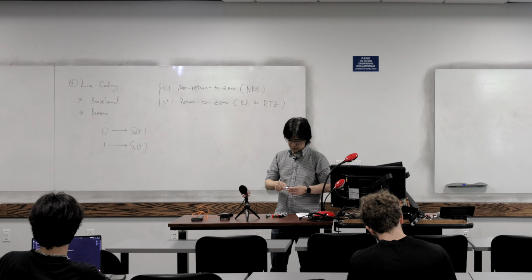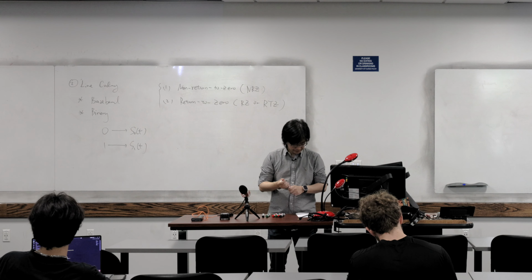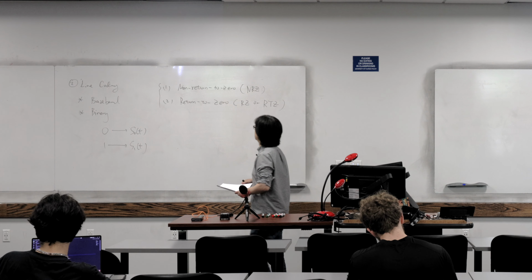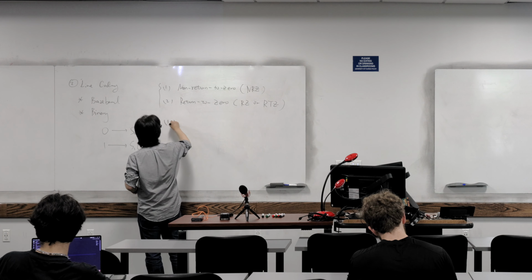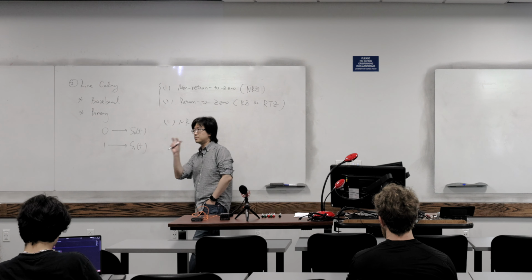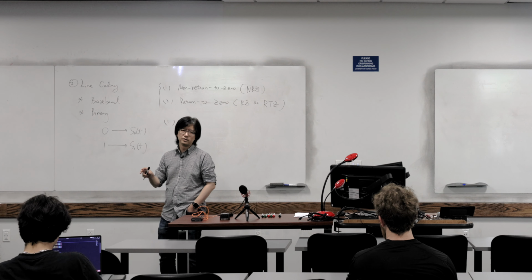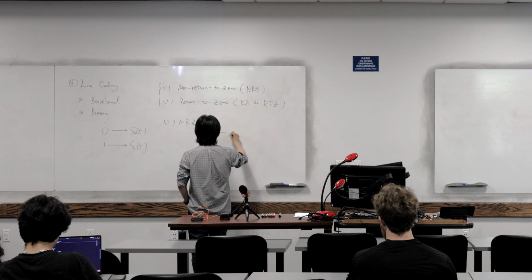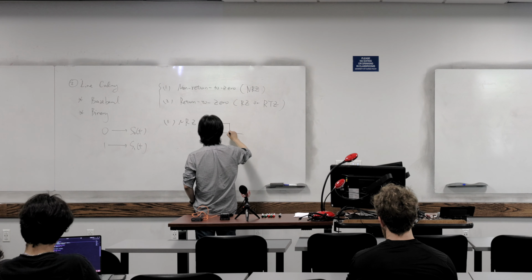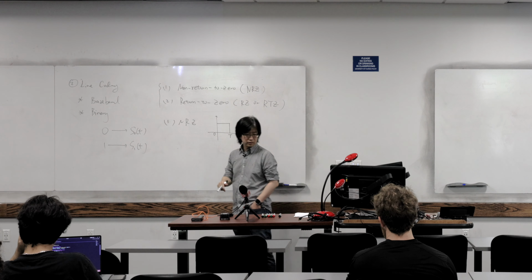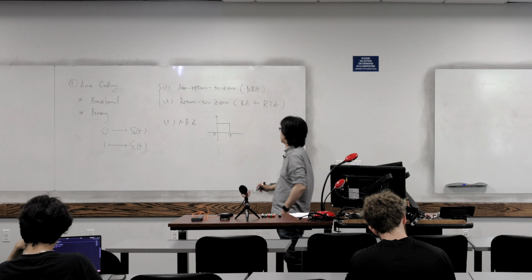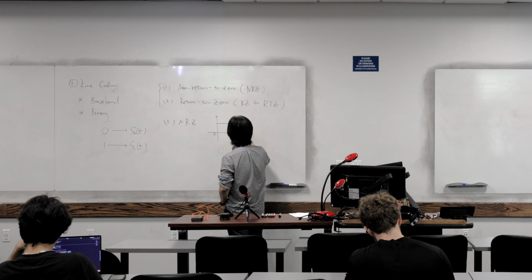The concept is very easy, so let's see what that means exactly. Let's see the first one, NRZ. Non-return to 0 basically means that during the symbol time we never return to 0. Let's say our pulse shape is like this, so the duration of this is our symbol time. We use T here, so this T is the symbol time.